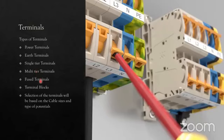Then you have fuse terminal. In some applications, you will need protection. So that fuse terminal will be having a fuse inside the terminal. So you can always select the appropriate fuse size, and in case of short circuit or anything, the fuse will blow, and the instruments or the PLC connections will be on the safe side in case of fuse terminal. But if you have a normal terminal, you cannot protect your PLC inputs or anything.